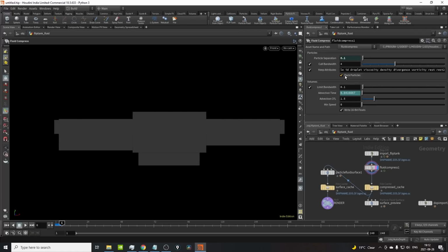And then it has the packed particles option. Packing particles is just nice, less disk space, it's good, very high resolution simulation. You're adding a little bit to the sim time by packing them, and you're adding a little bit of CPU time in the end by unpacking them. But if you're limited with disk space, it's definitely a really nice option to do.